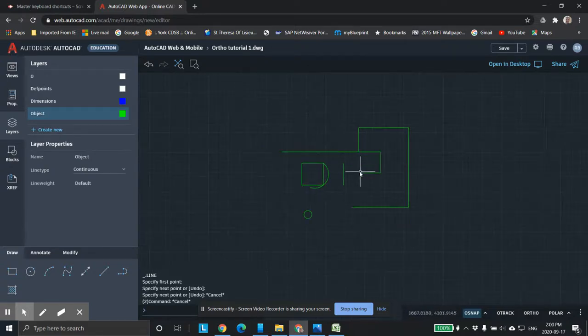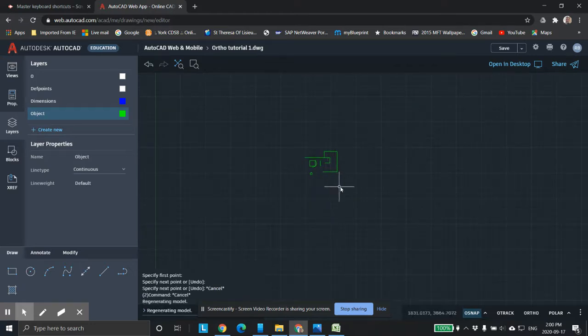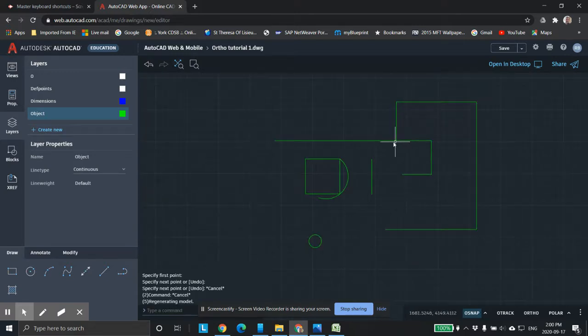In the next video, I'll show you how to start. We've got zoom extents here. Zooming in and out, I should mention, sorry. First of all, if I hold the middle mouse button down, I can pan around. I can zoom in and out using the middle mouse button, like so. And these here, this is zoom extents. So if it's way out like that, rather than going all the way in with the mouse, I could just hit zoom extents and it'll bring it into the full size.